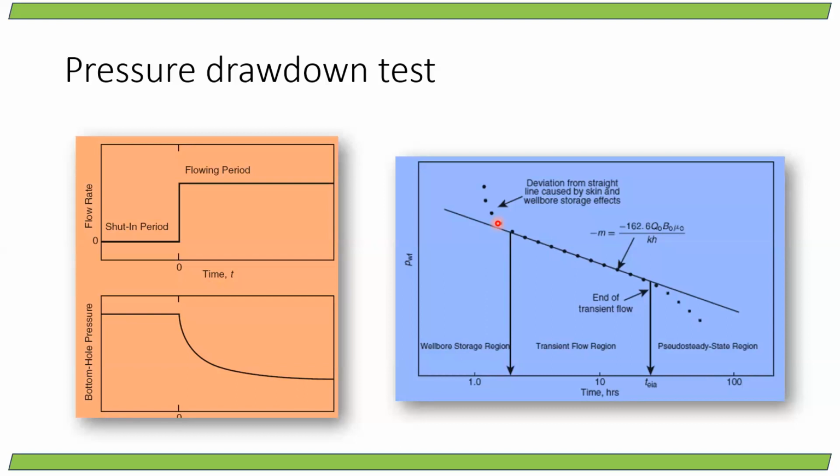These chemicals and other things will be inside your well, sometimes inside your annulus, that will fall into your wellbore horizon, where exactly oil will start to enter into your wellbore, near the perforations. Once it falls there, it will mix with oil and start producing with oil into your wellbore. We don't need these kinds of fluids at the surface.